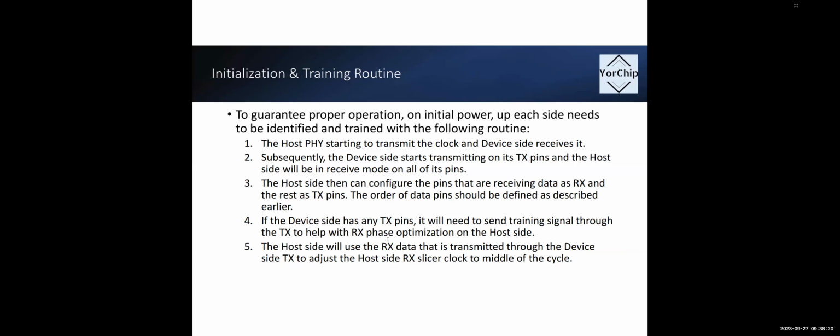There's definitely a limitation as we go up. Again, there are a lot of things coming into the picture. Process speed is one of them. A lot of times the chip on the other side is on a much older process, but also the length of the channel, because all those uncertainties start to add up, along with the mismatch between the lines.